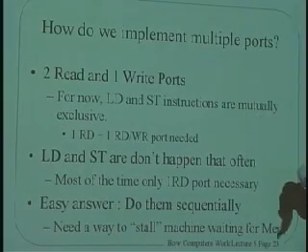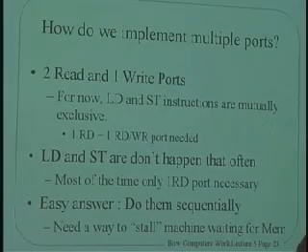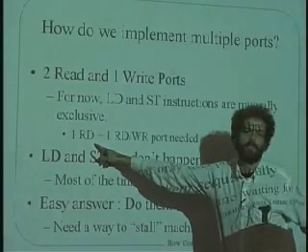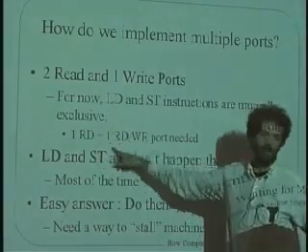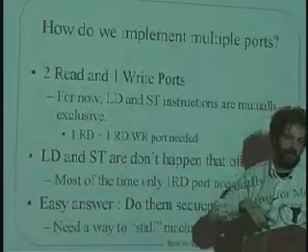With the register file, this is the big, slow memory. The register file, we were reading from 2 places and writing to a 3rd one all at the same time. But remember, the interactions with the memory are serialized by the fact that the big memory is accessed for only 2 reasons. One is to get what the PC points to and fetch the opcode. That's what you need the read port for. The other is to do load and store, which is what you need the other port, which sometimes does a read and sometimes does a write.